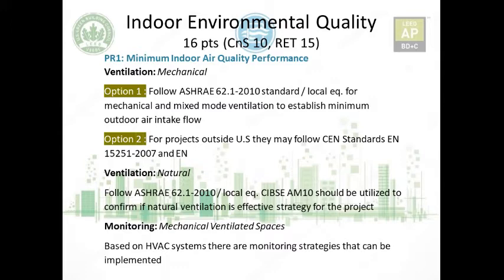For example, natural ventilation cannot deal with a humid climate. It cannot cater to humidity, so you have to use a mechanical ventilation system. In certain climates where the weather is harsh, whether it is too cold or too hot, natural ventilation might not be the effective strategy for the project. So if you are using natural ventilation, it should be confirmed by CIBSE AM10 that it is the right strategy.